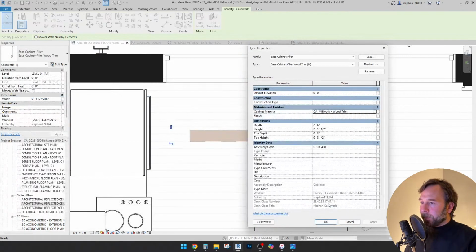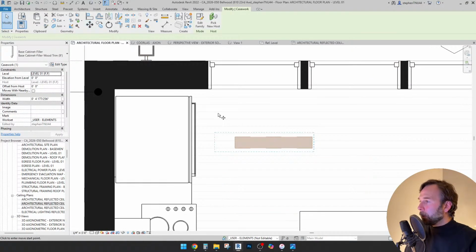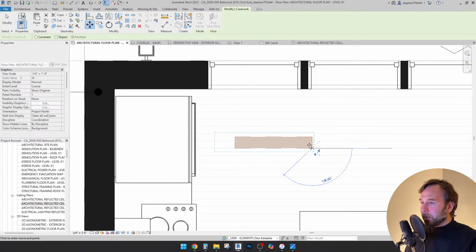Millwork, wood trim, okay. And the depth, we're at 30 inches. Height, we want to go 9 feet. And then, so actually, if we're doing this right, it's actually 8 foot 11.25 inches, because the 3/4 inch wood flooring is sitting on top of the slab on grade, we're not going to recess or depress that to compensate that depth. That all looks good.